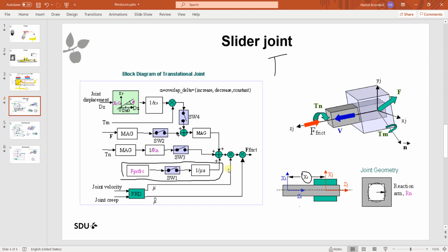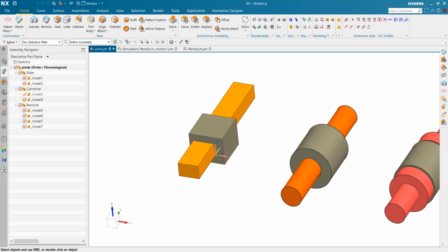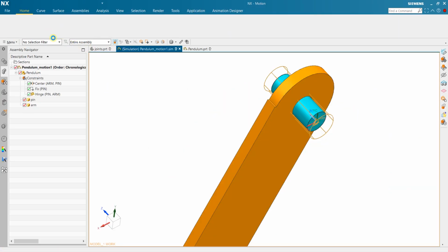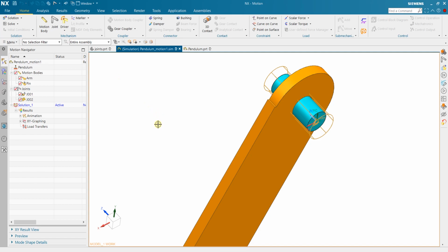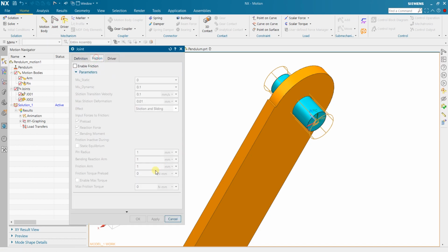So it will be calculated directly from the force, and it will divide it by friction, because here, if I go back again, you input the friction force, not the normal force. It's set like that because in experiment, you can calculate the friction force directly. You put a load cell on your mechanism, and you start to apply force until it moves. That will give you the direct friction.